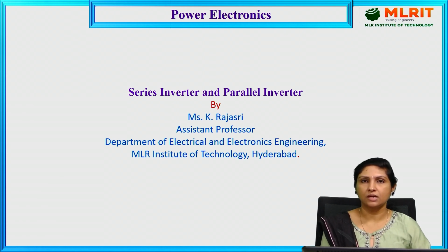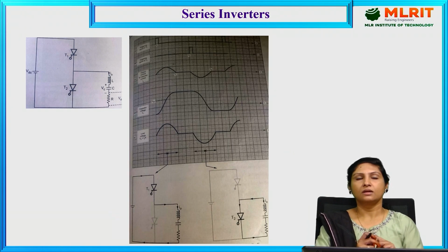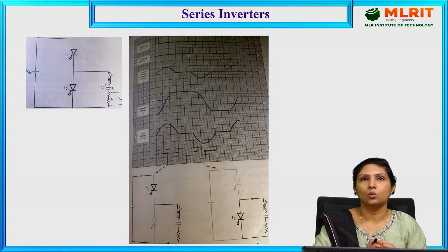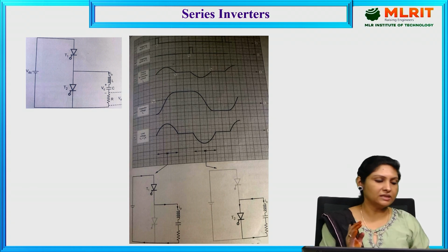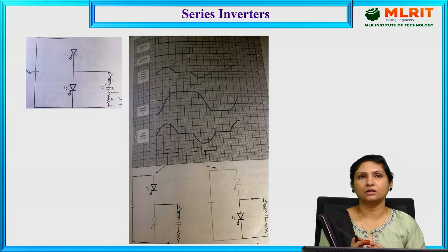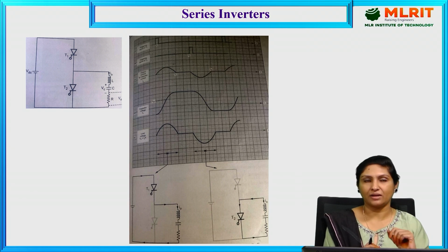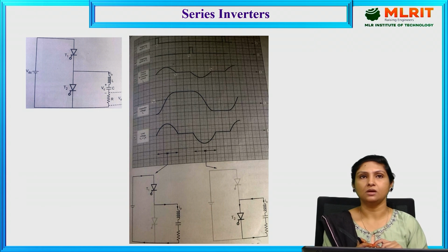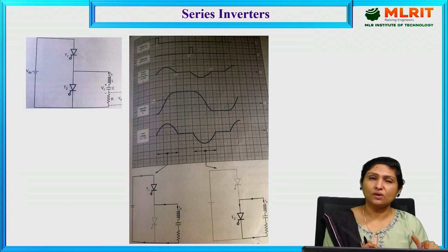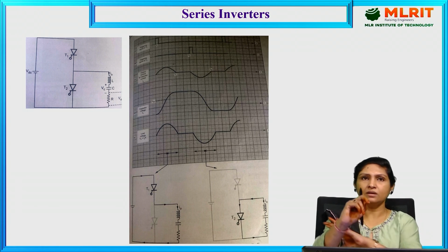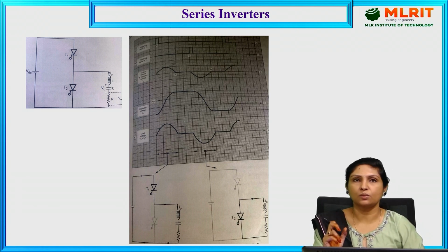And in today's lecture, I'll be discussing series inverter and parallel inverter. Here, let us firstly discuss series inverter. What is series inverter? In these particular series inverter and parallel inverter, we are making use of thyristors. So far, the inverters which we have discussed, we were only making use of transistors, or otherwise GTO, MOSFET, IGBT. Here in series inverter as well as in parallel inverter especially, we'll be discussing making use of thyristors.